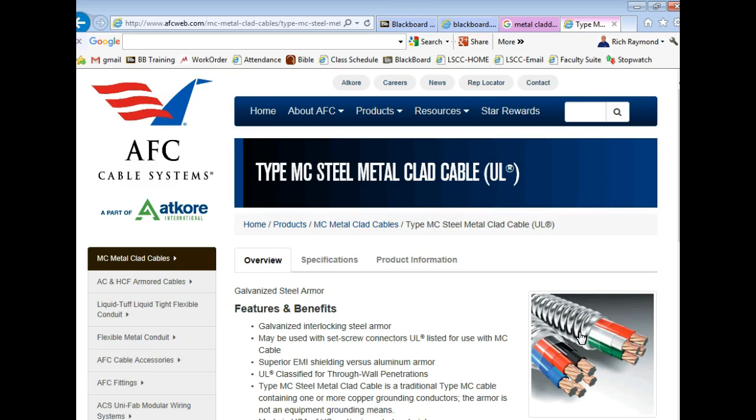Flexible. And normally, if I was to look up inside this plenum up here, which is the space between the artificial ceiling and the real ceiling, we would have boxes up there, and then running from them would be conduit carrying all the wiring. Dropping down to the actual light fixtures would be these metal clad cables.